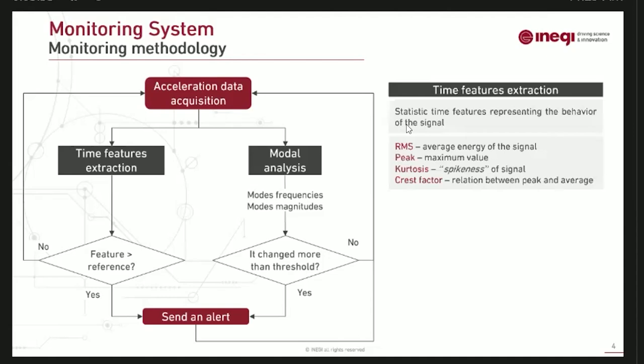Time features, as I said, represent the signal. This is a good method to analyze the data because it is much easier computationally, since we are representing a signal with thousands of points of raw data by about 10 points of data, 10 features. And we know that they represent what the signal is giving.